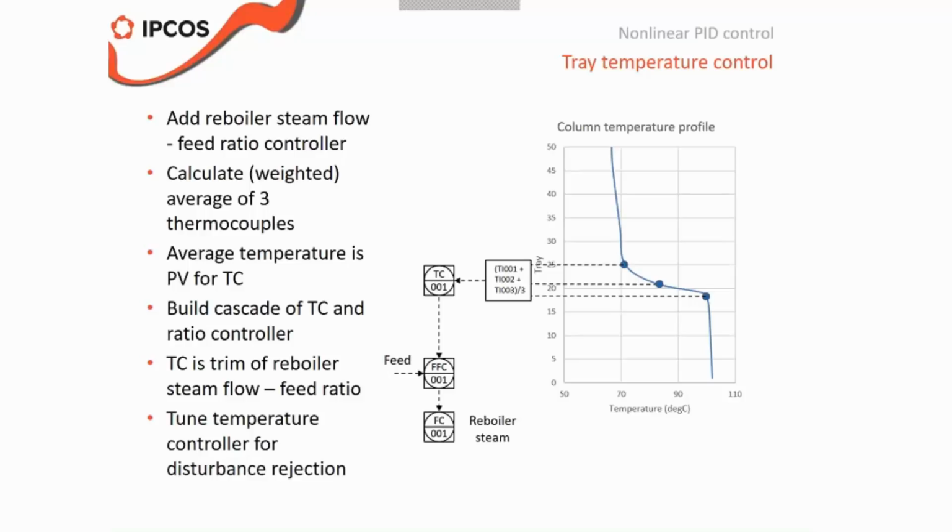And what also helps is if you have any modeling software, let's say you work with APC controllers and you have a modeling software to build the APC model, try to model for example the neutralizing agent flow or the ratio against the pH.